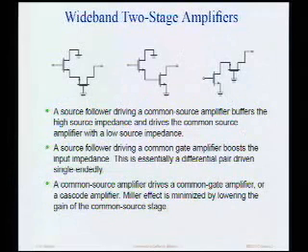So the cascode amplifier is probably the most widely used amplifier in basically integrated circuits because it's robust, it's cheap, it's small. I can lay it out very efficiently using a shared junction, right? I don't have to have 2 junctions here. I could just use 1 junction. I can minimize the capacitance I put on my cascode node, and so it's very popular.